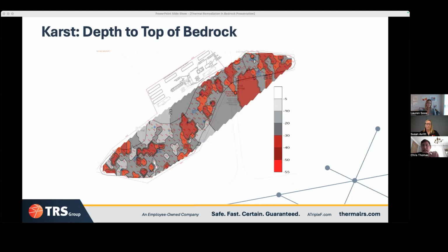And you might ask, we had sonic drillers drilling in real time. We had 2 rigs at this one site, this very large site in Alabama, and we had a whole construction team set up on the side. As soon as the driller was able to report that bedrock interface depth, we knew that we had another 8 feet to go. We'd report that to the electrode constructors, and we'd be able to customize this secondary element that was designed solely to heat that bedrock portion of the site.